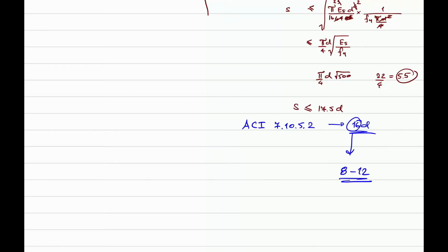because with a slender column you have more chance of elastic buckling of the overall column, and that will concentrate the moment and produce a second order moment in some area. In that area you will not expect uniform compressive stress, for a short column versus a slender column of the same size. A small column has a small second order effect.